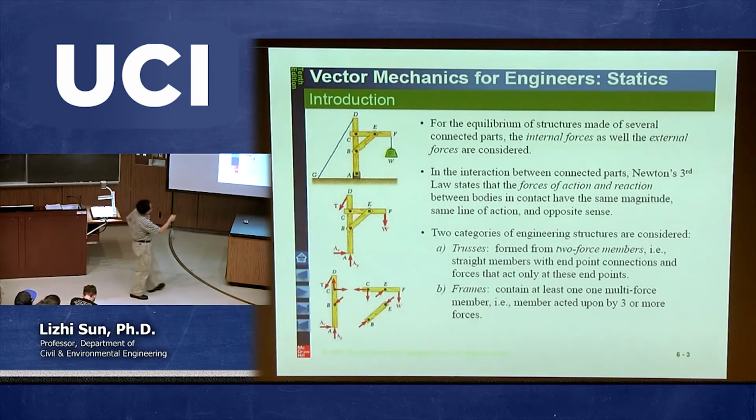Similarly, if you want to calculate the internal force at point C or at point E, then what you need to do is to plot this part of this 3D body, CEF, for example. At point F, there's still another force given due to the crate. At point E, because we cut here, this time there's a force acting on point E on this part due to this part of the 3D body.